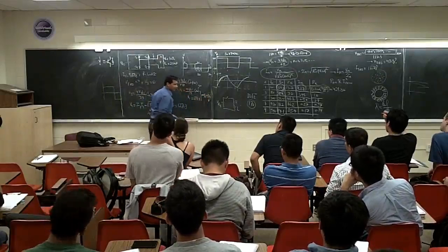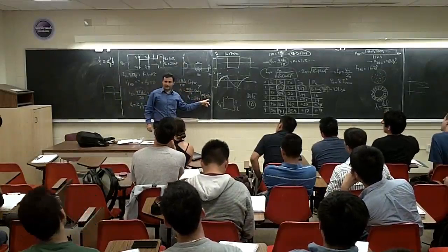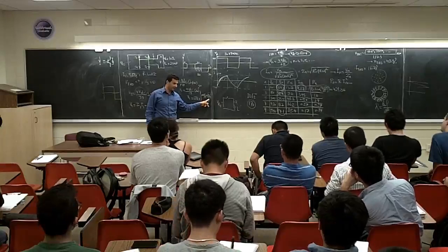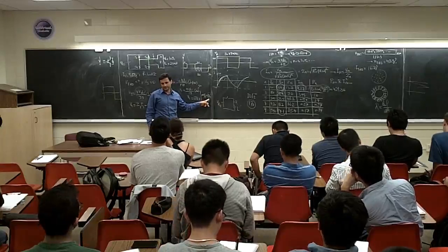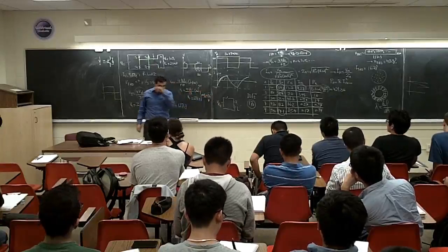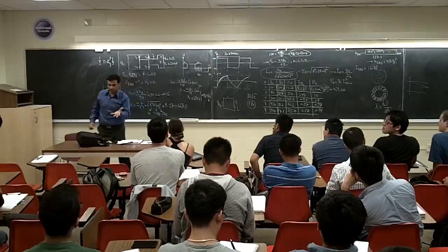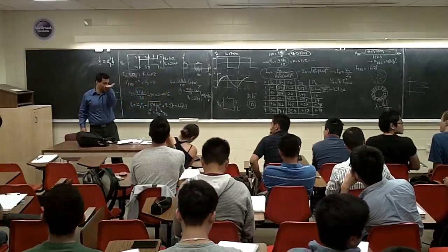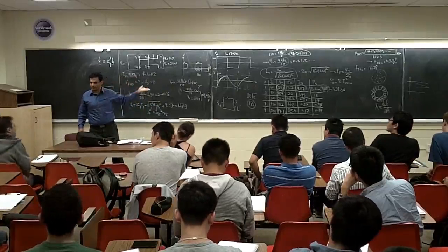See that here? Previously you had 100 volts. Now you have to have 116 volts. You need a bigger battery pack. So this is the effect of harmonic elimination. You are losing a little of your DC bus, so to compensate for that, you have to bring your DC bus higher, to compensate for what you are using.